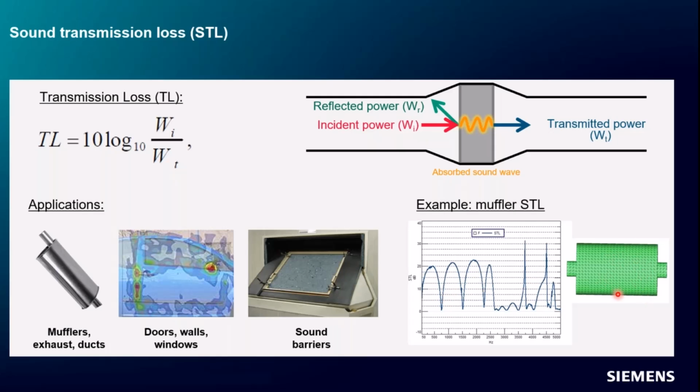And that's why your muffler or your exhaust system isn't just a simple expansion can. There'll be a series of expansion cans and perforated tubes and different chambers, and it's a much more complicated device than just a simple single expansion to cover more of these frequencies more equally.